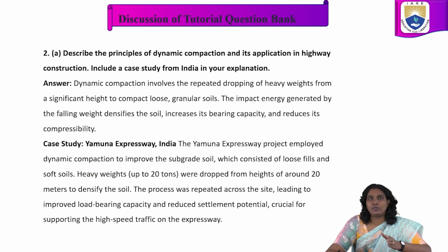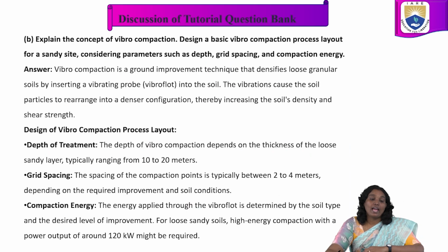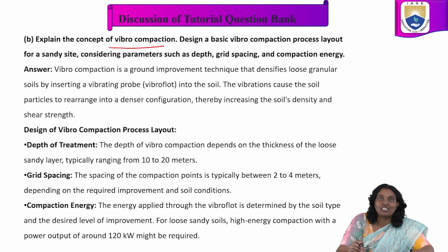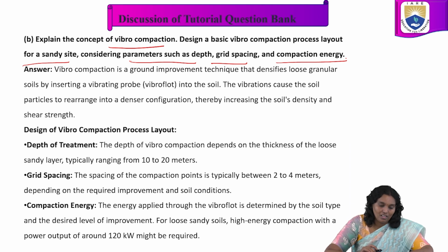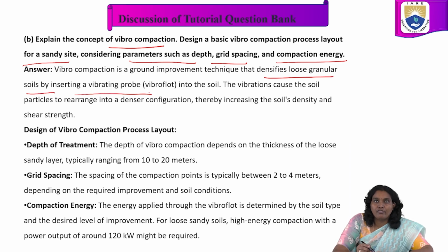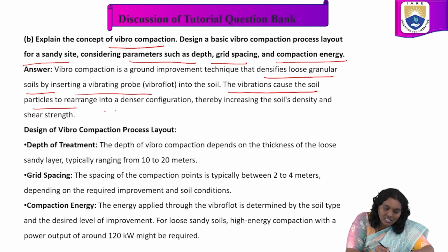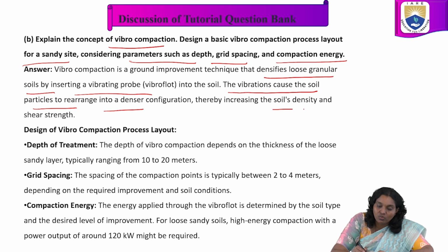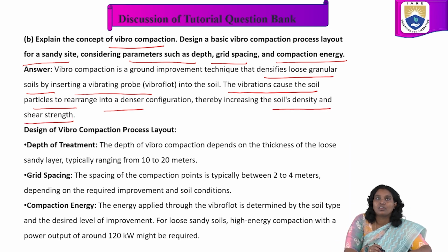Now, describe the principle. Already we explained this. Now explain the concept of vibrocompaction. Vibrocompaction is a ground improvement technique that densifies loose granular soil by inserting the vibro float into the soil. The vibrations cause the soil particles to rearrange into a denser configuration, thereby increasing the soil density and the shear strength. Whether the question asks for the concept or the principle, the answer is the same.